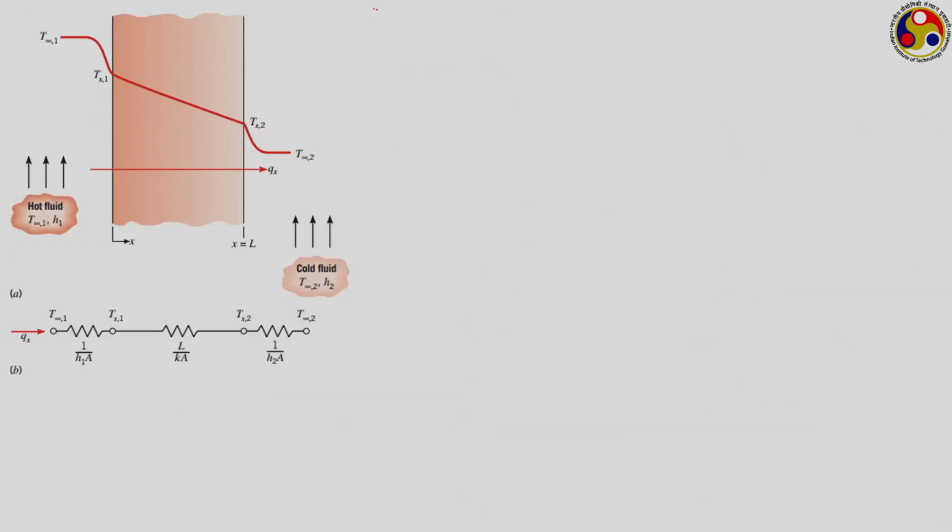So, we have just developed that the temperature profile inside your solid has become Ts1 minus Ts1 minus Ts2 into x upon L, and the conduction heat transmission in the x direction we have got to be equal to K A upon L into Ts1 minus Ts2.